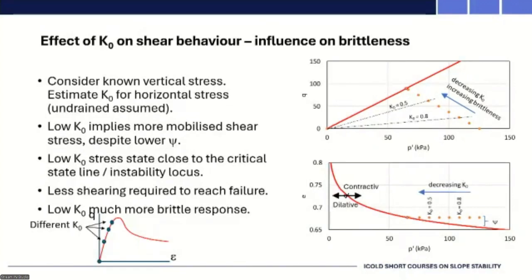Now I really want to point to the screen. So you can see if we guessed K0 to be equal to 1, we would have had a stress state there. As you start reducing K0, the values went to 0.8, 0.5, and ultimately close to 0.3 there. So without doing anything to the soil, but just varying K0, you are bringing the stress state very close to the failure envelope. What happens in terms of the state parameter at the bottom?